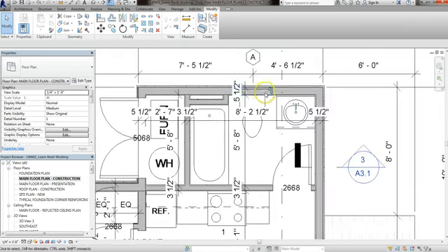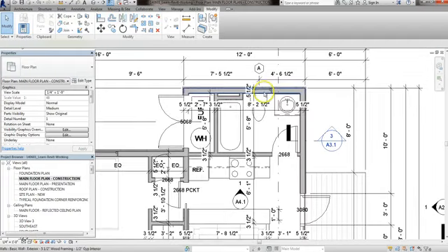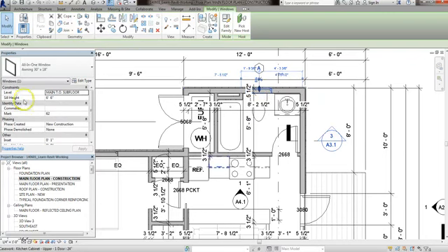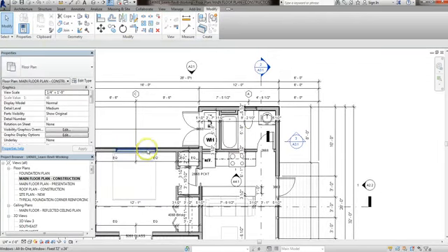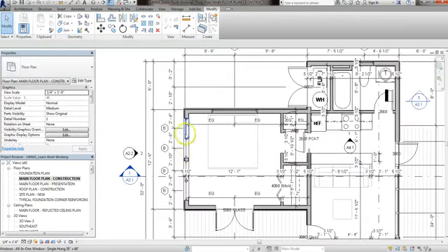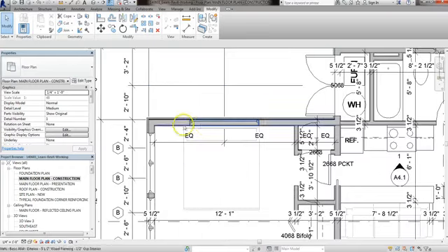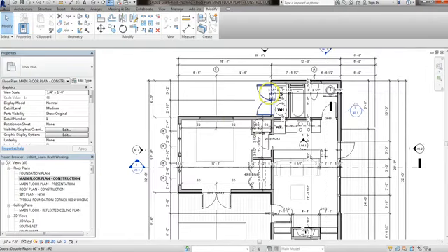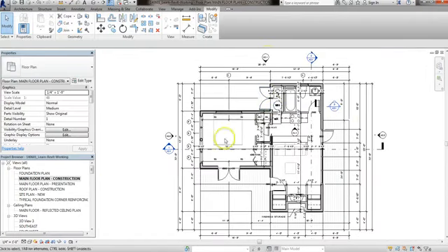One thing I'm going to show you is if you're putting in your windows, in the sections it'll call out your sill height and your head height, and you'll see that this one is a little bit higher. This one has a sill height of 6 foot 6 inches, and along with this guy, he's not looking like the other windows where you can see through and they're basically white in there. The reason why is that these are above the cut plane, and what a cut plane means is basically floor plans are drawn as if this was a real model of a real building, which in Revit now it is. That's one of the benefits of it, is that it's looking at kind of a 3 foot high view and down, and these are above 3 foot.